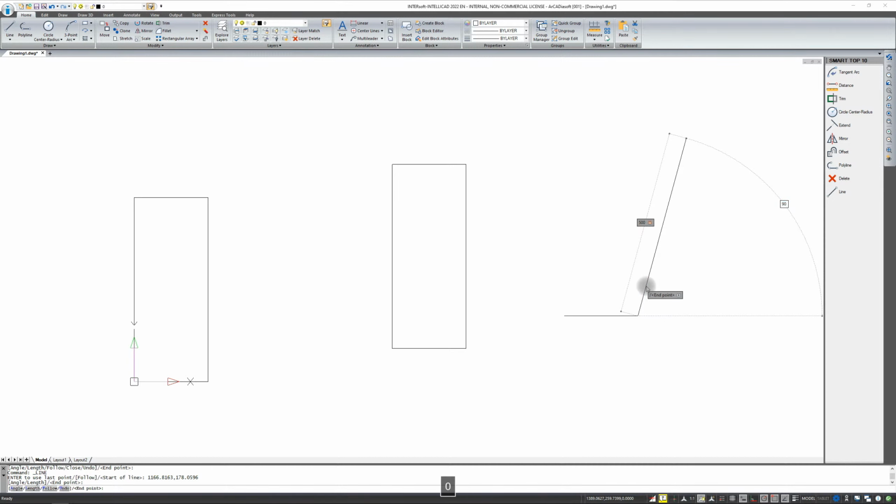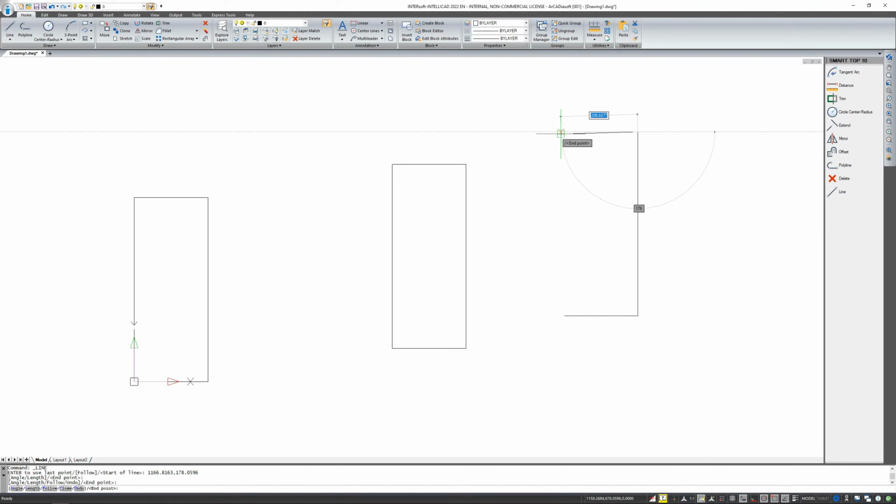Note that when I enter data in this way, sometimes the program treats the angle relatively. So when you define the end after switching, always check what the setting of the angle is. Now we have such a situation that if we look at the angles non-relatively, then downwards is at 270. Whereas now you see that from this line that I last entered, this angle will be 180 degrees because I'm going to the left. Remember that the program shows angles ascending in the counterclockwise direction.